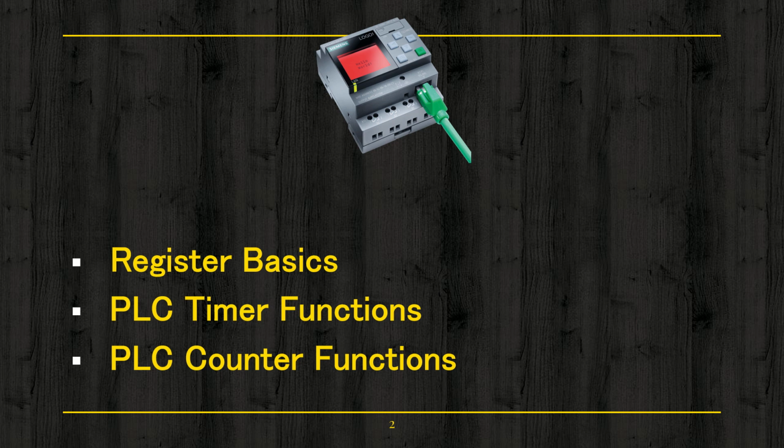Now, one important aspect that you need to know is that whenever we talk of these registers, we need to be very sure about the memory map of the PLC. As far as the syllabus requirements are concerned, I am not supposed to talk a lot on the memory map. What I will do is supply you with the memory map of the PLC-5 by Allen-Bradley.